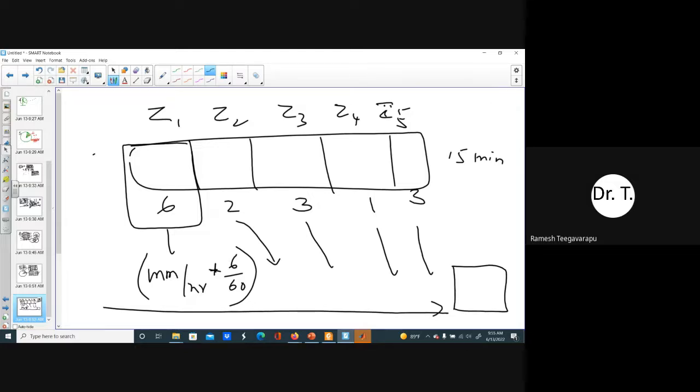So that's your 15-minute total. And once you have the 15-minute totals, then you can compare with the rain gauges to see how good they are quickly. And then those 15-minute totals can be put into your distributed hydrologic model. So it all depends on the temporal scale at which you are running your distributed hydrologic model.